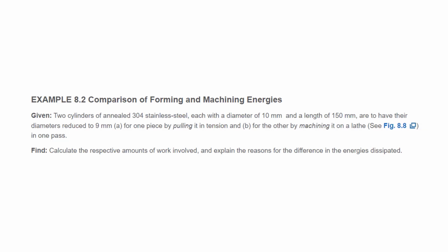And then from table 2-2.2, we can calculate this K and N. So for strain energy, for this material, K equals 75 megapascal, and N equals 0.45.